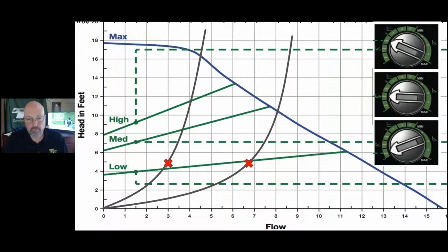And it takes a long time to change too. We need to see a certain drop in flow or certain change in flow for at least an hour before it's going to decide to change a performance curve. So again, it's a nice story. Hey, press the button, I don't have to do a thing. This thing's smart, figures it out. I am relieved of the responsibility of pump sizing. It's just not how it works.